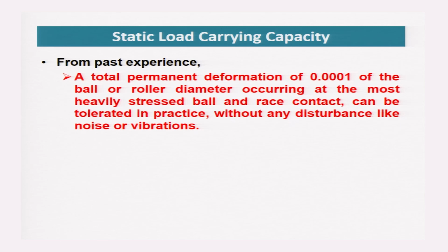From past experience, it has been found that a total permanent deformation of 0.0001 of the ball and roller diameter, that means if the ball and roller diameter is d, then 0.0001 times the diameter, at the heavily stressed ball and race contact can be tolerated in practice without any disturbance like noise or vibration.